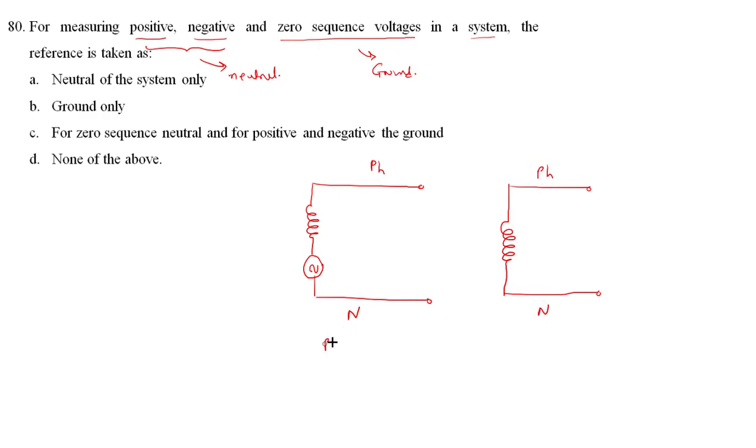So this is the positive sequence network of a three-phase generator delivering a current. This is the negative sequence network. Now the zero sequence network, depending on the connection, if I assume that our generator is solidly grounded, then its network diagram will be something like this. So here we take this as earth or ground, and this one is our phase. This is the zero sequence network.